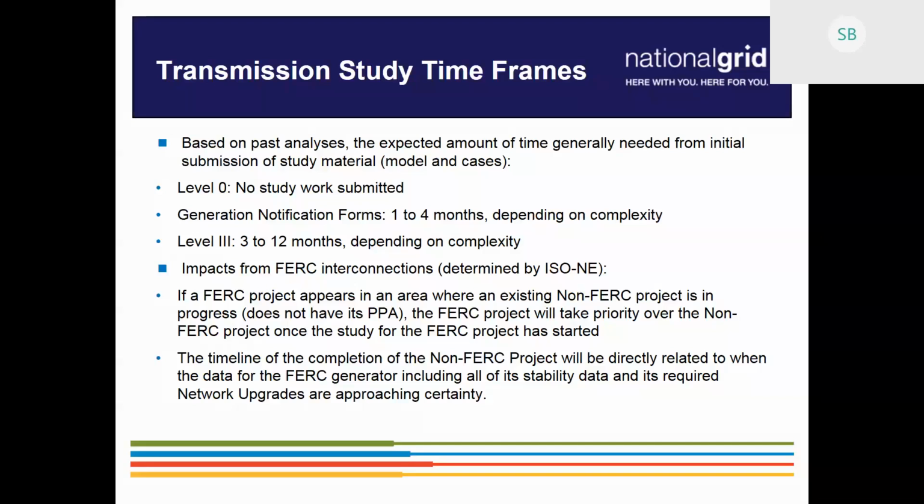To the point of projects that are in SMART and potentially also participating in ISO markets, the ISO has identified the potential need for a transmission service agreement in addition to the ISA. Where would that be identified within this process, or is that a separate process? That's a completely separate process. If you've applied to the ISO for interconnection through Schedule 23 or 22, Schedule 23 is 0 to 20 megawatts, and Schedule 22, I think, is over 20 megawatts at the ISO level. That's right. So whatever their process is, you would follow those separately.